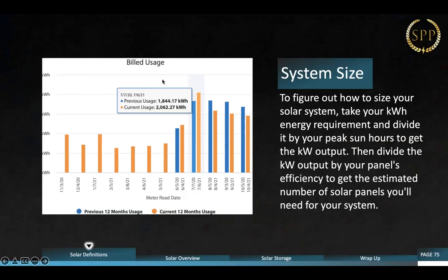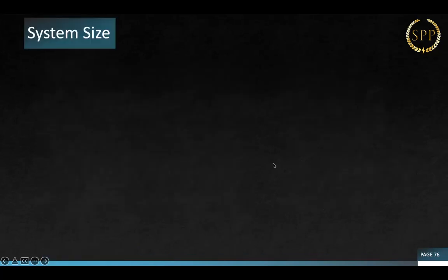You guys get a picture of the graph on the bill, or you get the annual kilowatt hours, or you get the monthly kilowatt hour consumption. It's always better to have a monthly or the graph. And here's the reason why. You see how this spike happens right here from July all the way through October for this customer. This tells us when we're going to need the most power so we can set the proper tilt for the customer. This is one of the functions that we need in order to be able to do it.